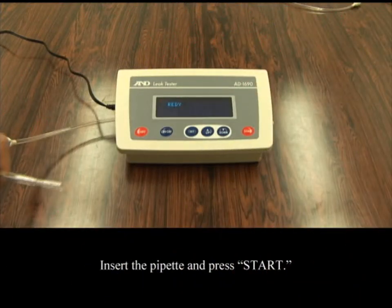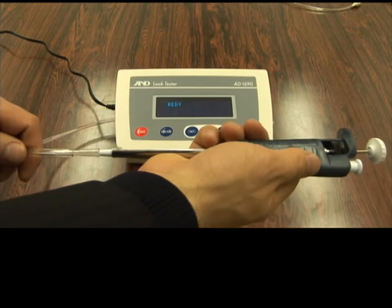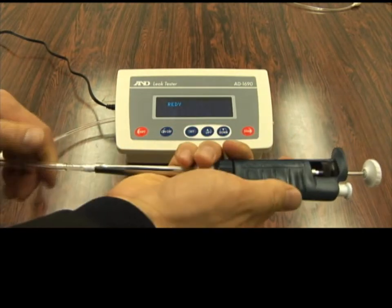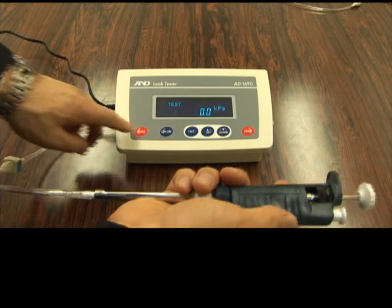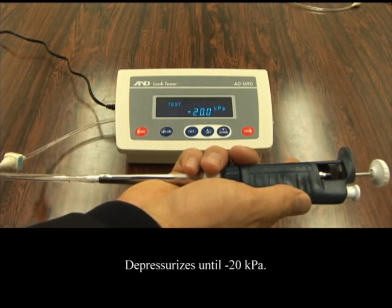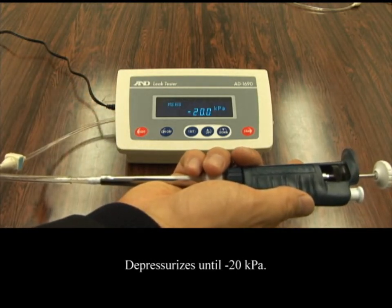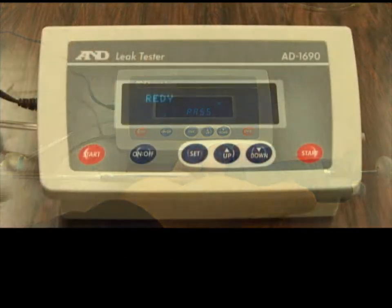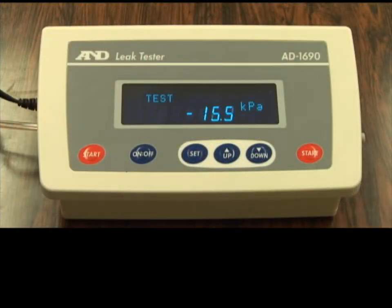Finally, insert the pipette into the tip of the attachment and then press the start key. The pump starts and depressurizes until -20 kilopascals. The AD1690 displays pass for leakage at or below the set value and fail for leakage above the set value.